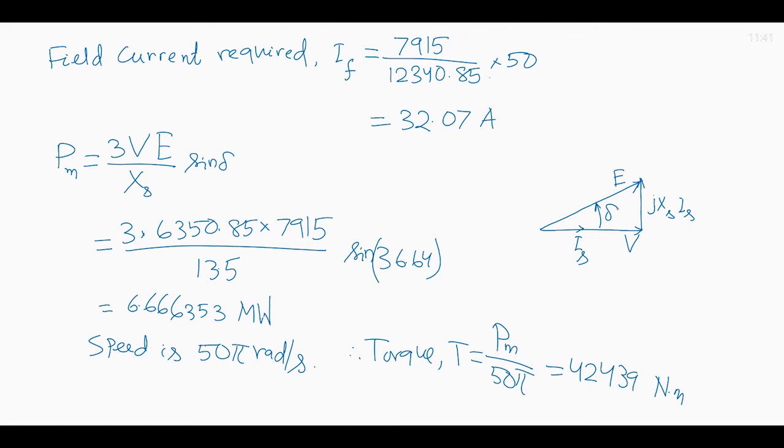You see, in a motor, the cause of rotation is the applied voltage to the stator, which produces the rotating field, and because of rotation induced EMF is generated. So, induced EMF is the effect and the cause is the applied voltage. So, in a motor, V is ahead of the induced EMF. This is for generator. This one is for generator.